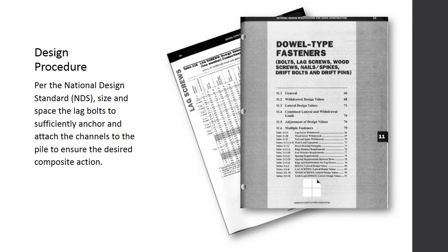Per the National Design Standard, size and space the lag bolts to sufficiently anchor and attach the channels to the pile to ensure the desired composite action. To simplify construction, lag bolts rather than threaded through rods are recommended.